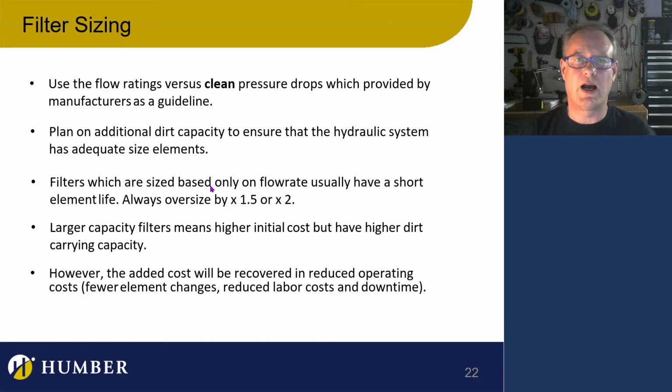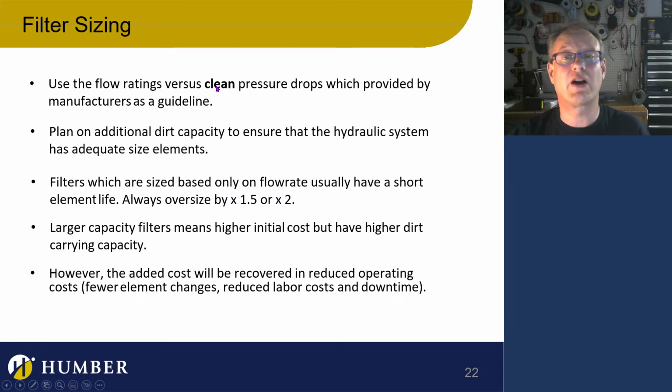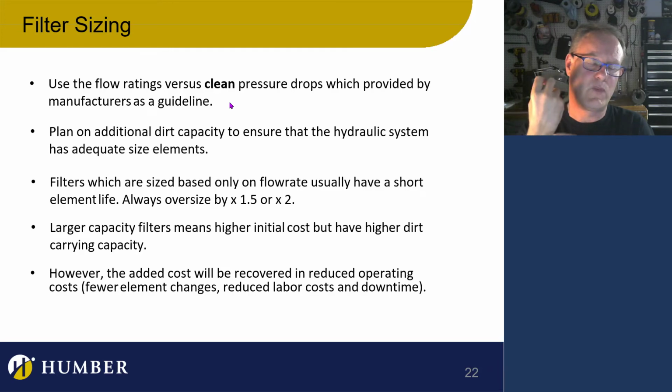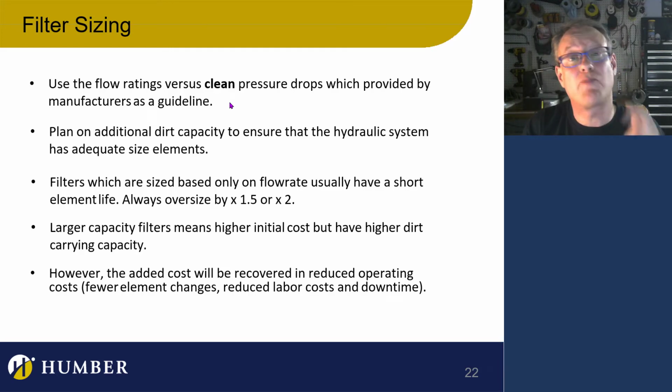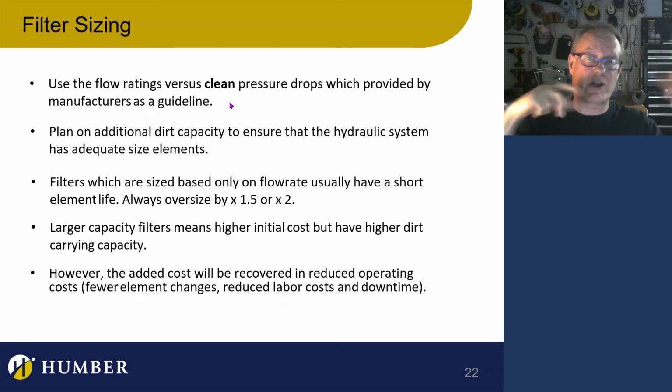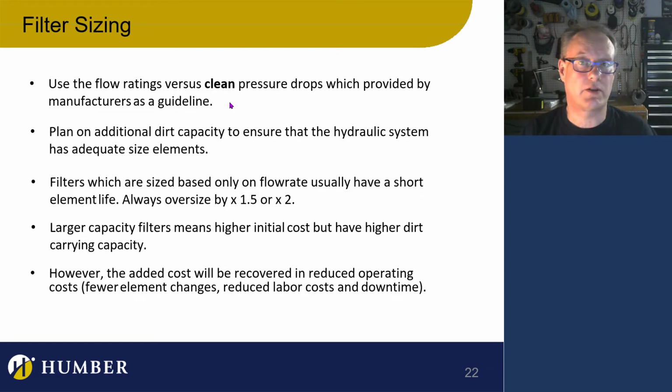Okay, good. So I'm going to jump back to one of the other slides here because it's really important to talk about this. Again, filtration is so huge, I'm going to stop and do another slide on this. I've highlighted the word clean here: the flow ratings for a clean pressure drop. So essentially, when you look at a filter, it's going to have pressure drop ratings, right? We took a look at that slide before, where the pressure drop and the flow rate are looked at. And that's for a clean filter. It's for a clean filter.